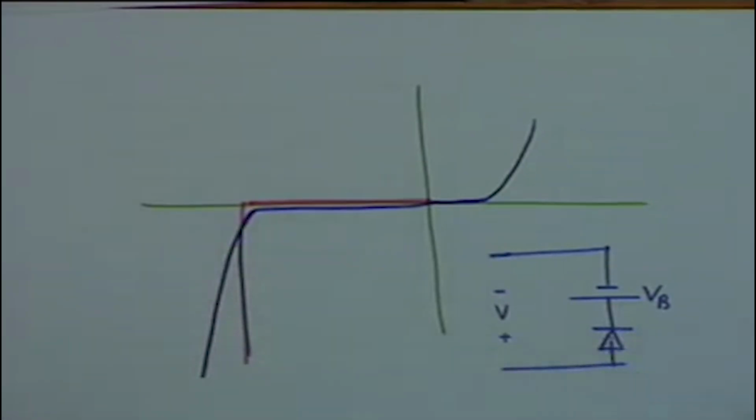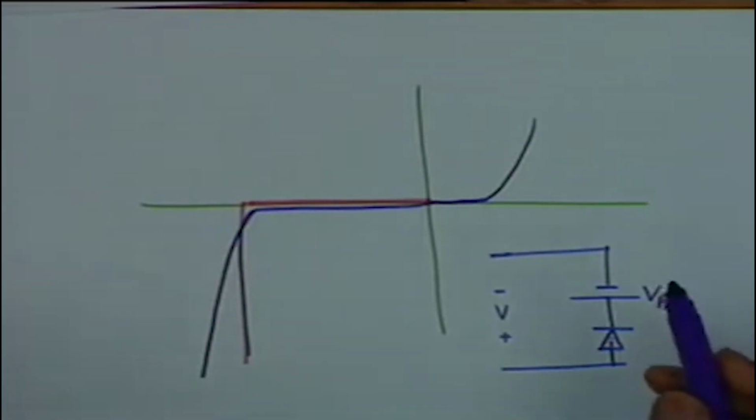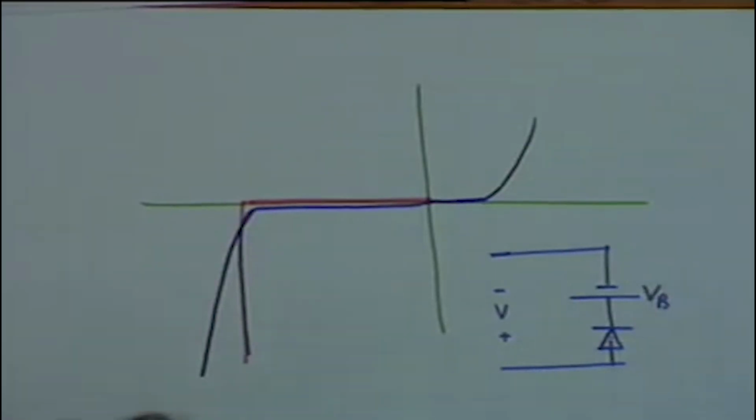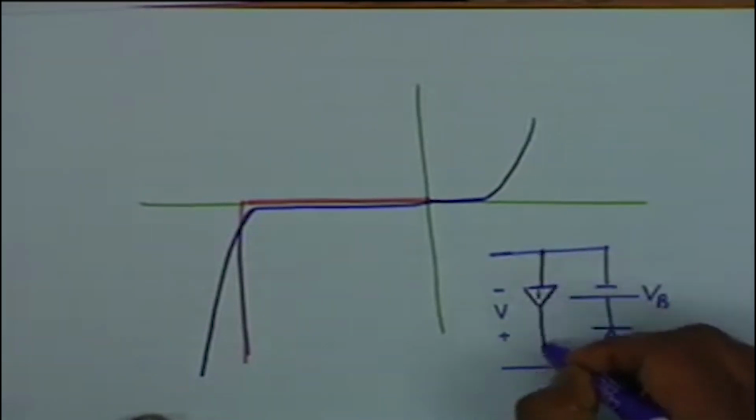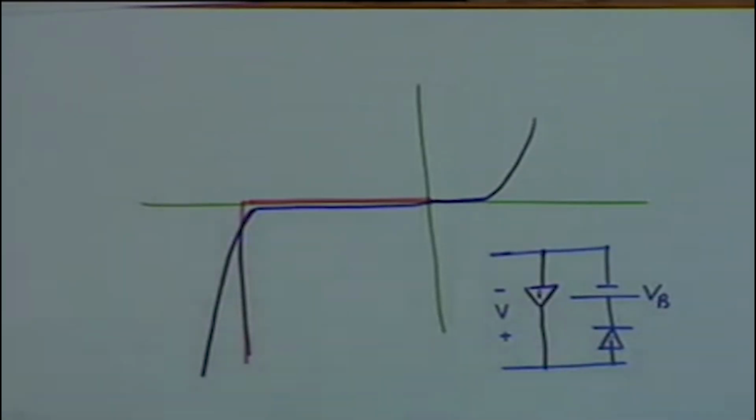After that, if it is the red curve, then we have approximated it by an ideal diode. Now, if you want to include its behavior as a normal diode, obviously you should put an ideal diode here, or an ideal diode in conjunction with the threshold voltage, RD, reverse saturation and all that. Now, since we are not using a Zener diode in the normal operation, we can forget about this. Is that clear? We are only considering the equivalent circuit when it is used in the Zener region, or the Zener mode of operation.